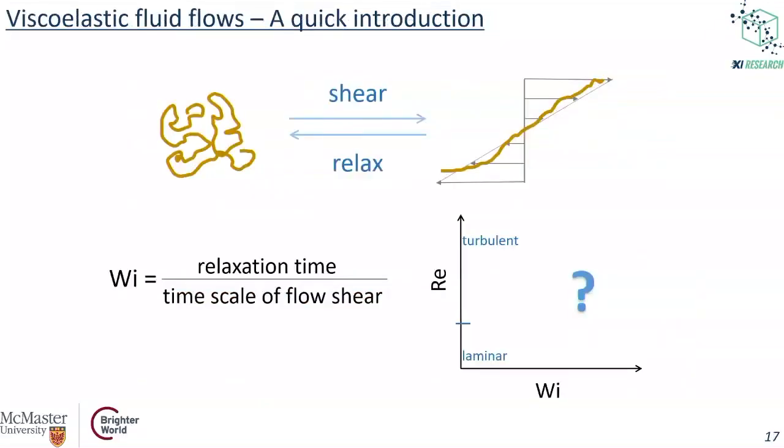The reason is that a polymer is a complex molecule which can interact with the flow motion. When you have a polymer in a turbulent flow, the shear force and extensional force are going to stretch the polymer chain apart into a more extended form. And the entropic force of the polymer will try to make it coil back. The polymer is like an elastic spring. It always wants to coil back whenever the shear force is removed.